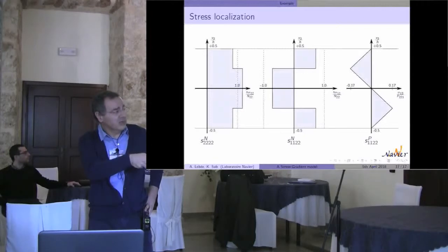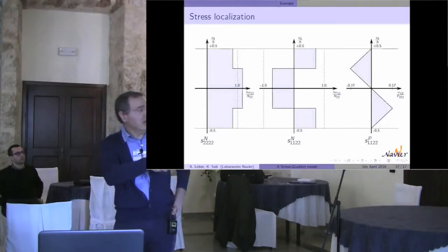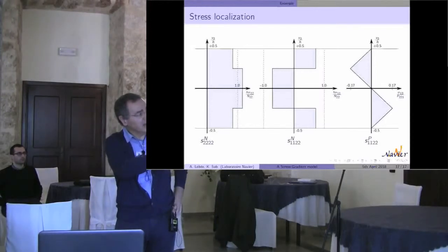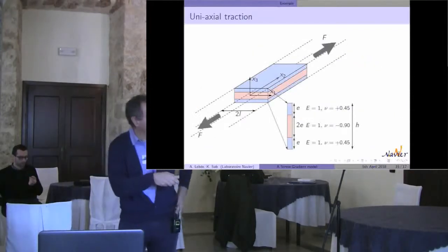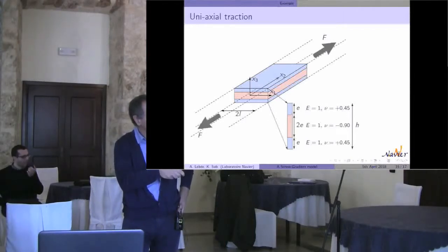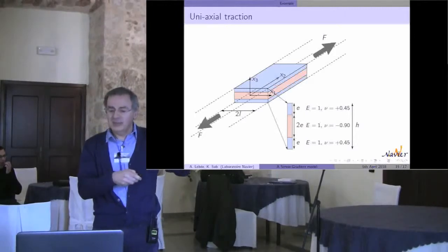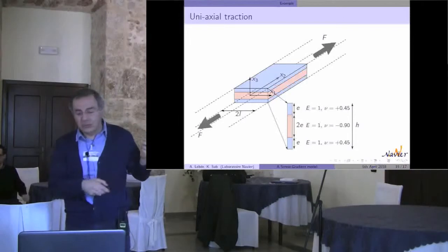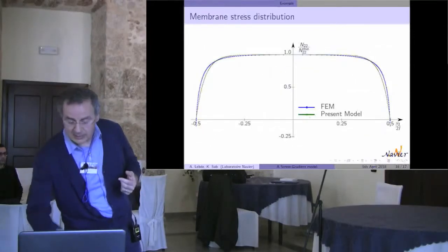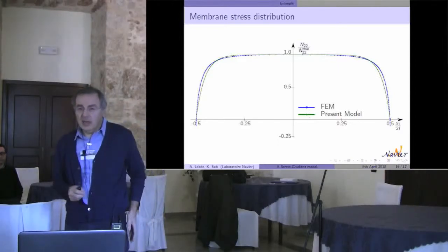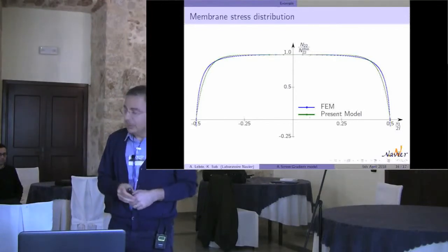But we have different values here with 0 as average, and this is sigma 1, 3, obtained by integrating this over the thickness. So if you want to obtain at this boundary sigma 1,1 equal to 0, and you have imposed that sigma 1,1 is obtained by the calculation of n22, so you have to impose that n22 is 0. So this is the explanation of this strange boundary condition that is obtained by our model. I think that I have presented you the main feature of our model, and I thank you for your attention.